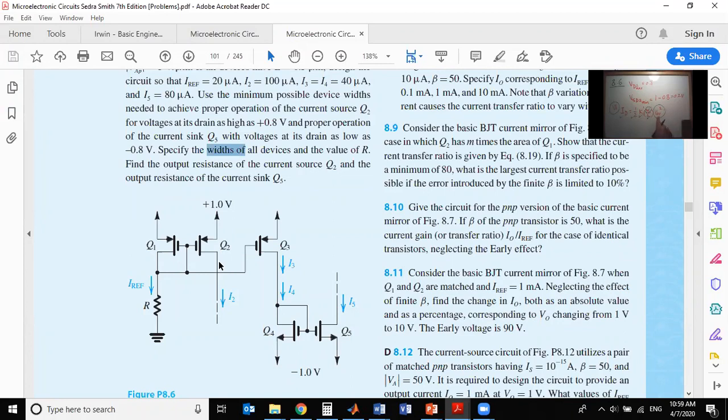Yes, but we're not gonna find VGS. We're gonna find V overdrive from the other condition. Remember the two conditions? We said that V overdrive equals VGS minus V threshold. But the other one, we have VDS is greater than or equal to V overdrive. These are the two conditions. I wrote these two equations before, okay? And this is for NMOS.